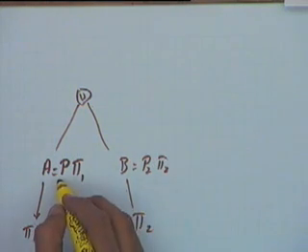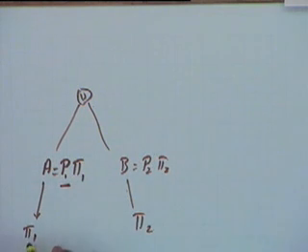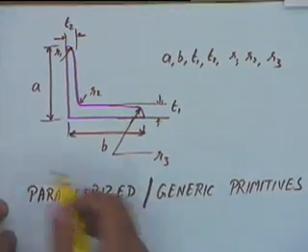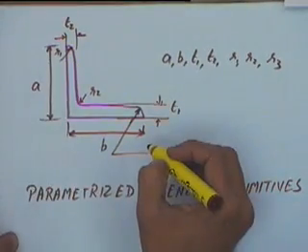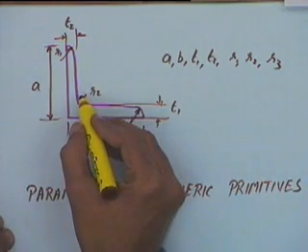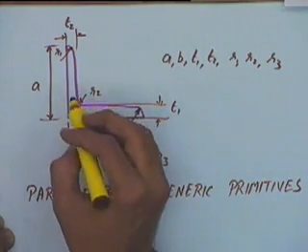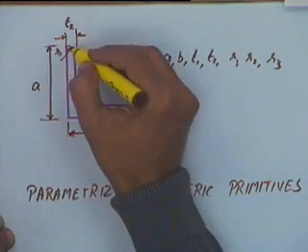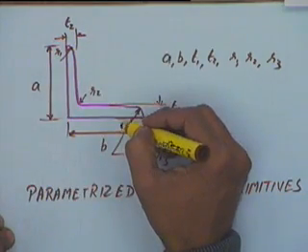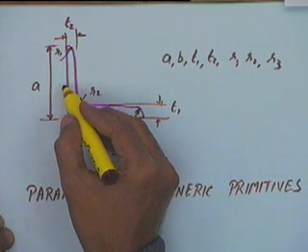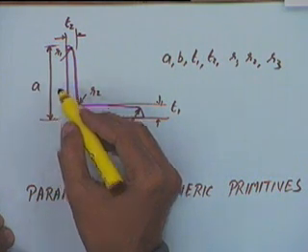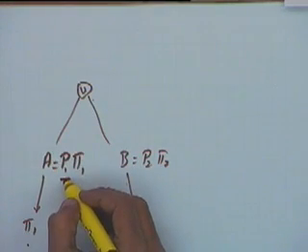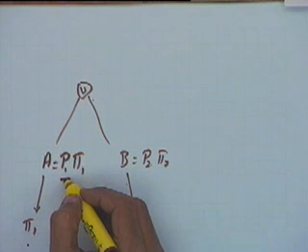Okay, so this process of instantiating a parameterized primitive gives us, in some sense, a family of primitives which have the same topology, the same adjacent surfaces. Surface adjacencies are the same. Even if I take a different value of T2 or T1, my surface interaction is not going to change. This process of parameterization is similar to the process of transformation, in the sense that it does not alter the boundary model. It does not alter the topology of the object.